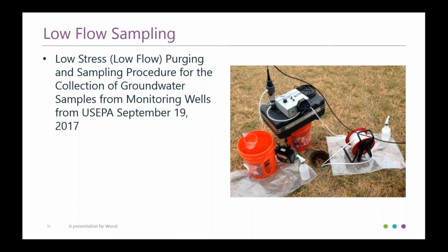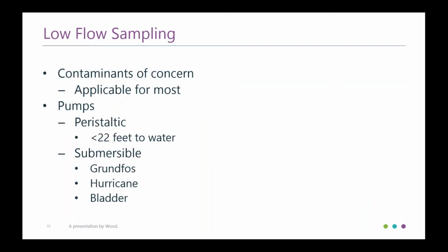You have a water level meter, peristaltic pump, looks like a YSI field parameter meter, which has dissolved oxygen, conductivity, oxidation reduction potential, pH. Missing anything? I think it has turbidity, but turbidity is probably not best done within the flow cell. You should have a separate meter. You can see in the next picture, in a couple of slides, you'll see a picture of a bypass that I think is the preferred way to set up to do that turbidity reading.